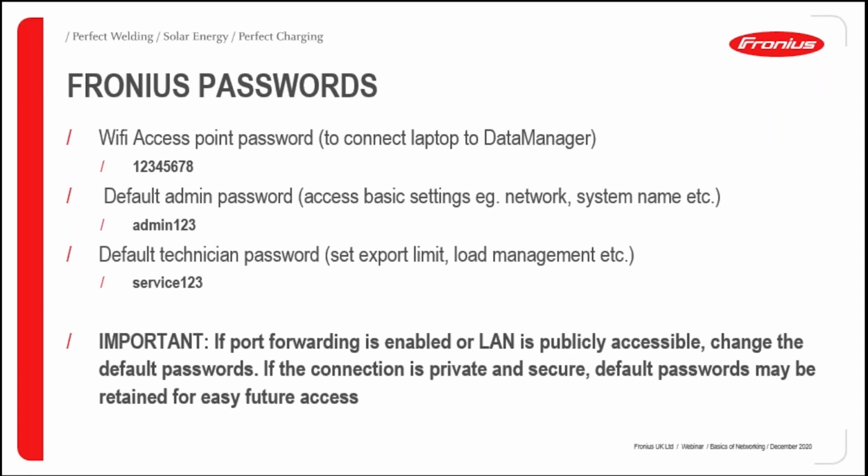And also, FRONIUS has a number of passwords as default. So to connect the data manager to your laptop or to your phone through Wi-Fi, you'll need to use the password 12345678. We then have a default administration password for setting basic settings such as network connections and system names, and that is admin123.